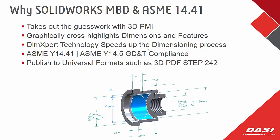There's cross-highlighting between the actual features and the dimensions, and you can visually see the associated requirements for a feature. We also help support your compliance with ASME standards Y14.41 and 14.5. They're kind of combined now. And we can also help you publish those technical data packages into universal formats such as a 3D PDF or a STEP 242.